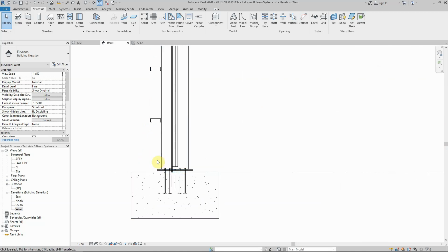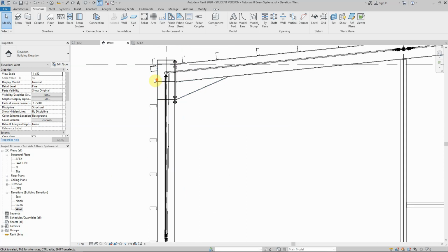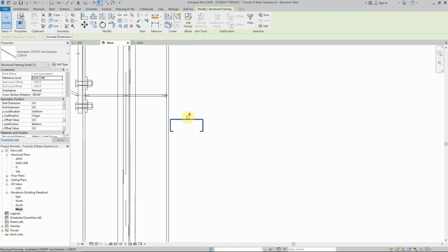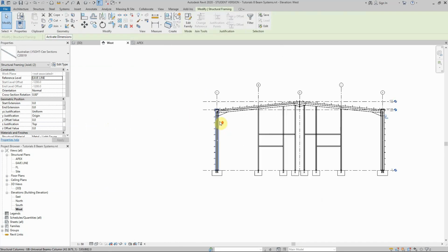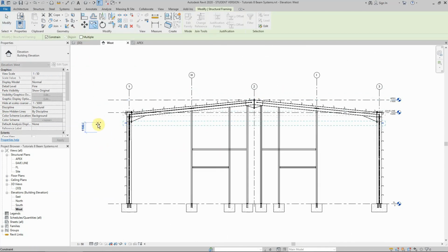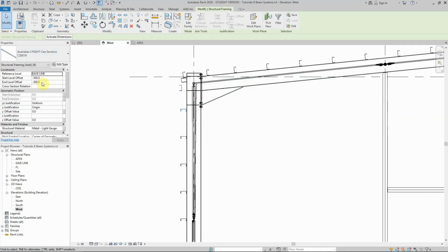Obviously, there's no girt, we've got 0, so let's keep it at least 200mm from the floor level. And we need to add another additional girt somewhere here, so we can support the wall sheets there. So if I select this girts here, and these 2 here, got to press Control, these 2 on both sides, and I can copy these to the top side. Let's say we copy them about 900mm, and we can adjust the rotations on those to be 180. Sorry, it should be 90.